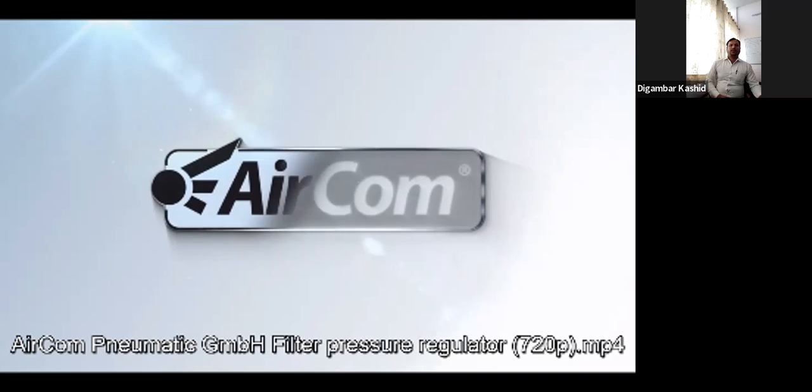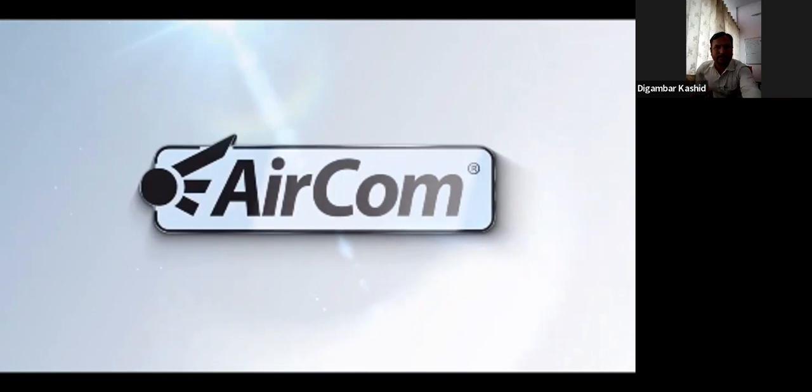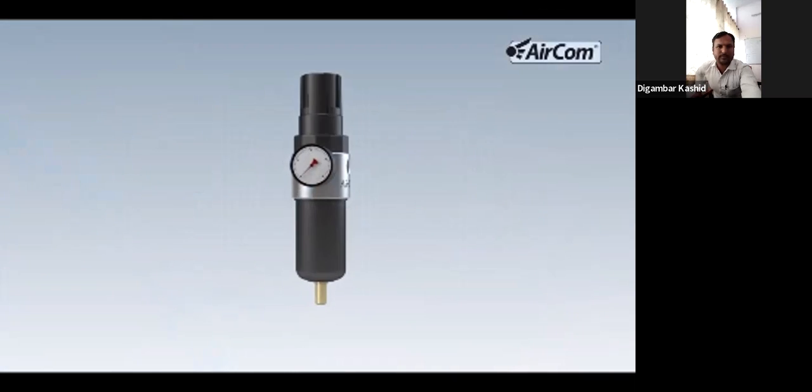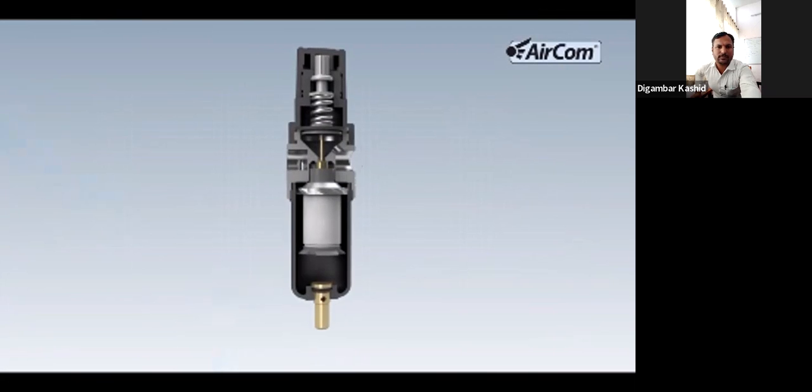One more video. Aircom Pneumatic, the specialist for pressure and volume flow control. Function of the filter pressure regulator. A filter regulator consists of a pressure regulator and a filter combined in one device. The regulator part consists of an adjusting knob, a pressure spring, a diaphragm and a tappet. The filter part consists of a twist cap, a filter element, a divider and a drain.